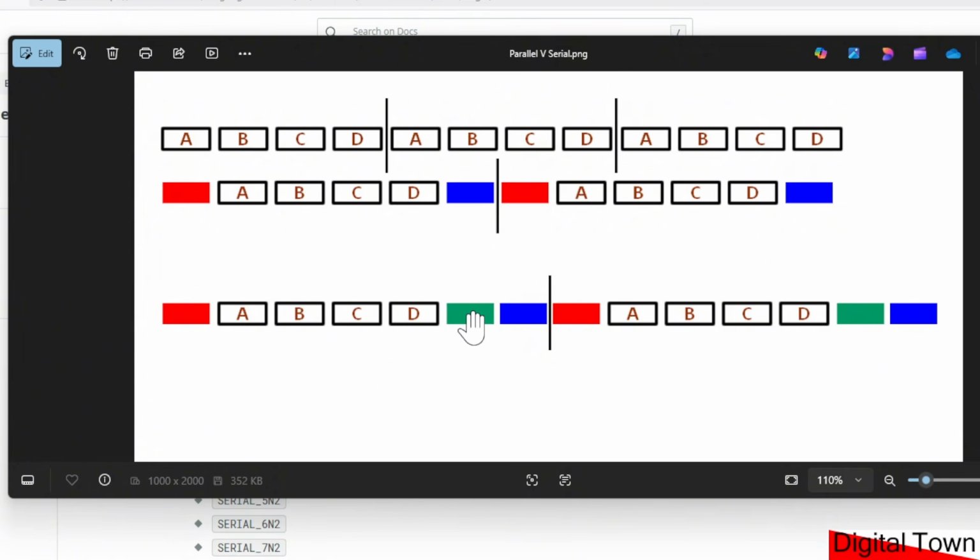Now you'll notice it's only sending 1 byte. Why not start adding everything together? Well, the problem is the more calculations you do, not only does it become slower, but the more data you are then sending over. If we're sending an instruction once a second, that's not going to be a problem. But if you want to start sending things every 10 milliseconds, and you have too many items in your transmission, it's going to take more than 10 milliseconds to send it. So the checksum is a way of checking the data and making sure that we can pretty much say that value is correct.